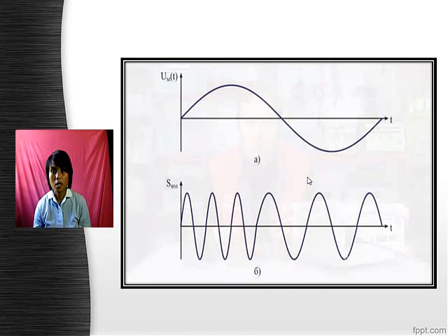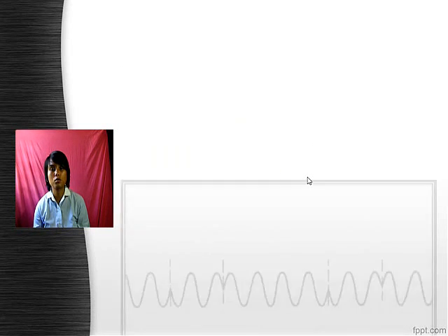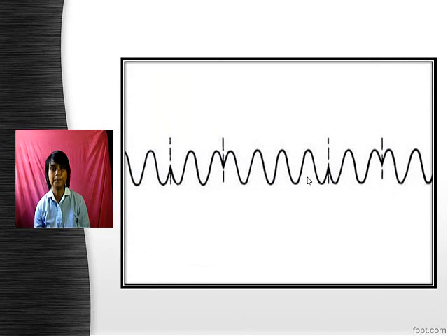The transmitter power amplifier operates at constant signal amplitude, so there are no special requirements for its linearity. The transmitter does not require a high power audio signal, so its scheme and design turned out to be simpler than a single side band transmitter. During phase modulation, the phase of high-frequency oscillation varies in accordance with the sound signal. The maximum phase deviation expressed in radians is called a modulation index. When you change the phase of the signal, the frequency also changes, as the frequency is actually the phase change over time.